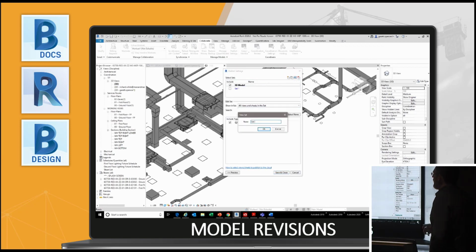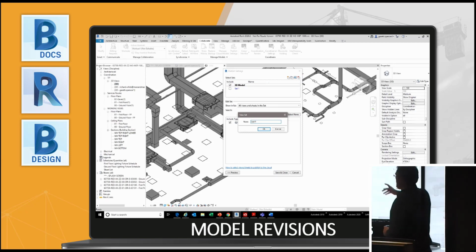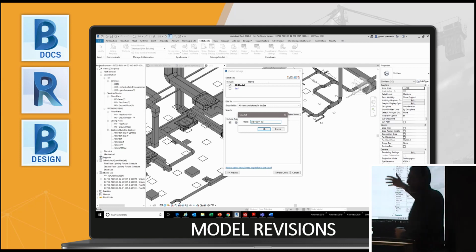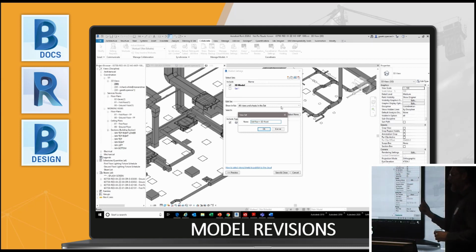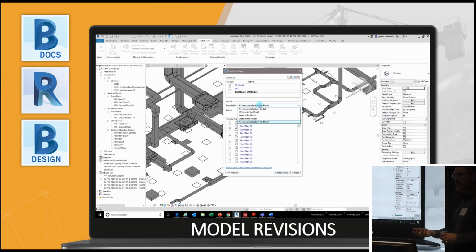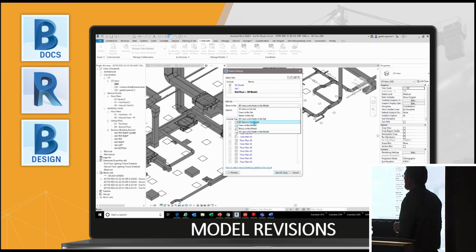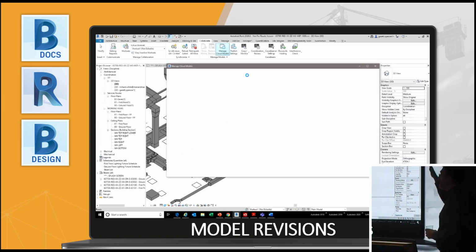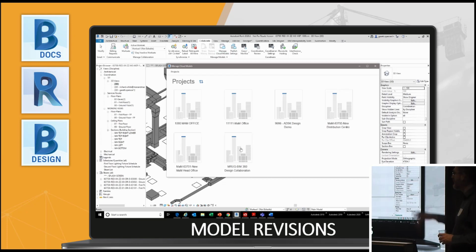So you can see here, just sharing some more information this time. So you can create your own little packages to share, whatever those packages you need. So for example, 3D model is great, but having a plan view, for example, can help when you're sharing information. You can see here, just going through, and save asset. Okay. So the ones that you have ticked, when you publish it, they will go through to BIM 360 and sit in the cloud as a new set.